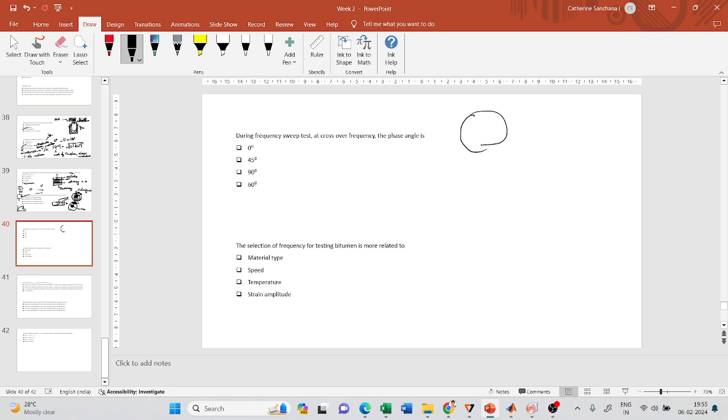So coming to a small amplitude oscillatory shear experiment, there are many ways of testing the material. I said that we subject the material to a sinusoidal oscillation with an amplitude and a frequency. Frequency, let us call it omega. Now I can play around with these values and probe the material in any manner.